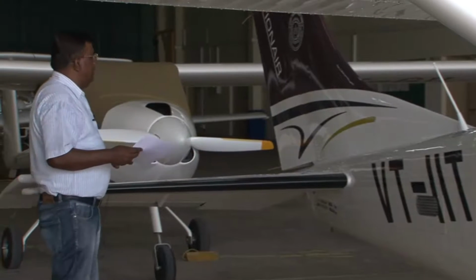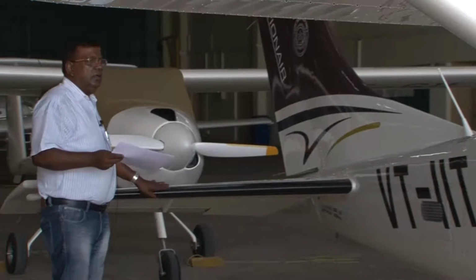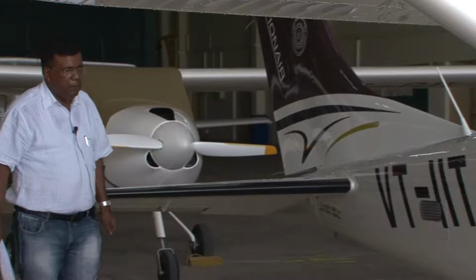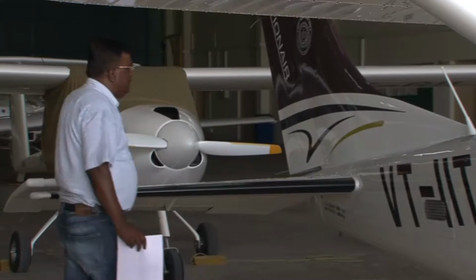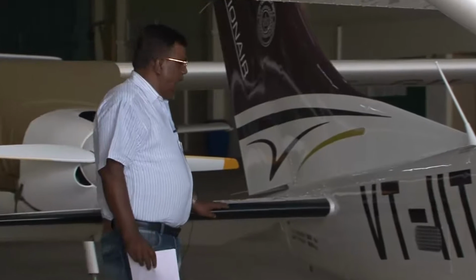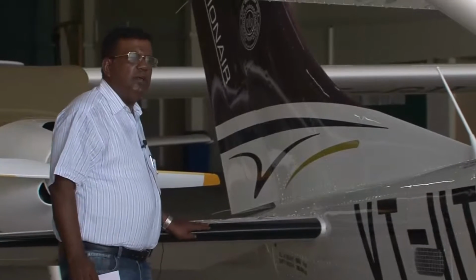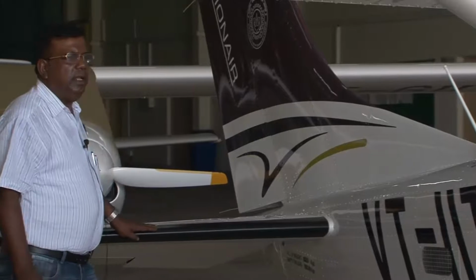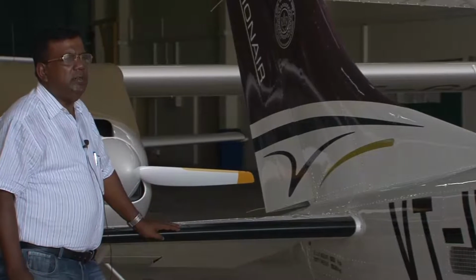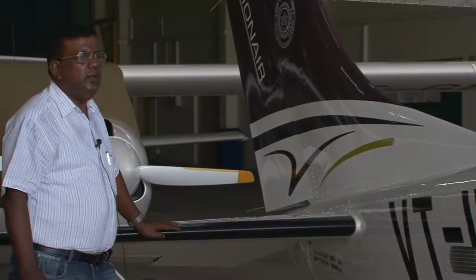This is very important information when you are trying to conceptualize, and you will realize that these dimensions have an important effect on the overall stability of the airplane, how we are going to design the stability of the airplane, and stability will be directly connected to handling qualities.